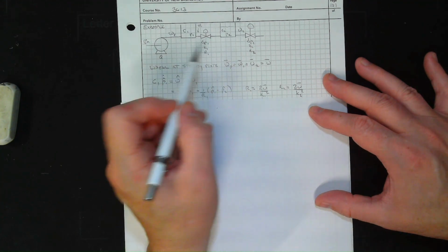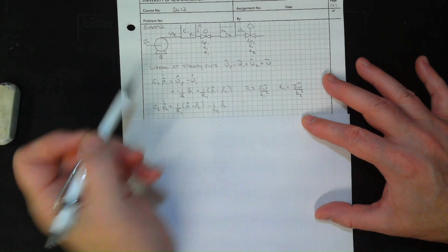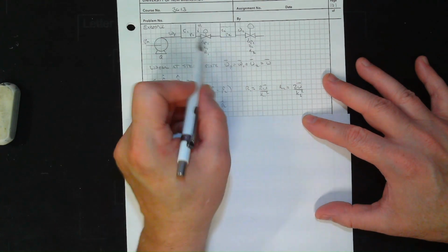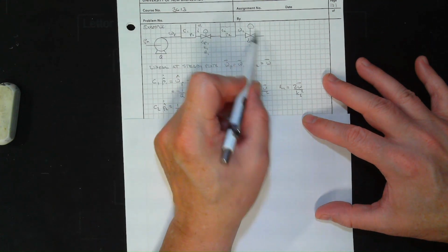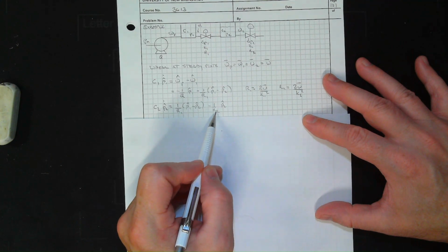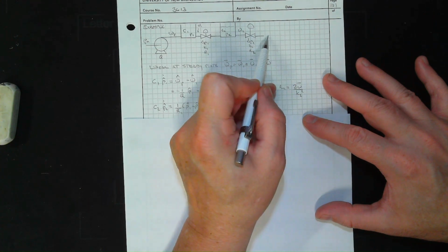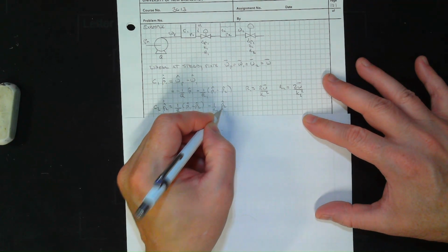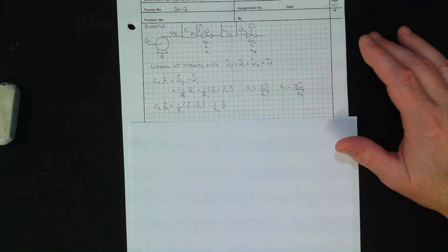Then we have another tank. Every time we see a tank, it's like every time you see a mass. So here we have C2, P2 hat dot equals, we have the flow in, 1 over R1, P1 minus P2, minus, we have another valve here, R2, minus 1 over R2, P2 hat. But it's going out to atmosphere, so that's just constant. The static terms have been eliminated to create a dynamic differential equation. Make that a little easier to see. And we're all done.